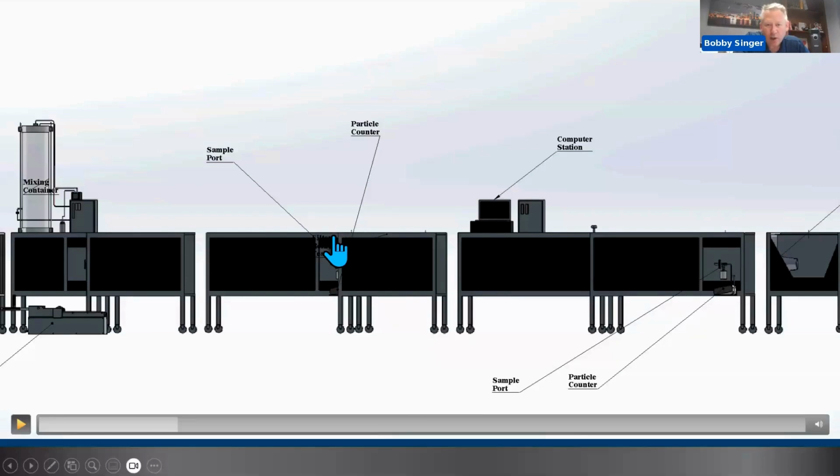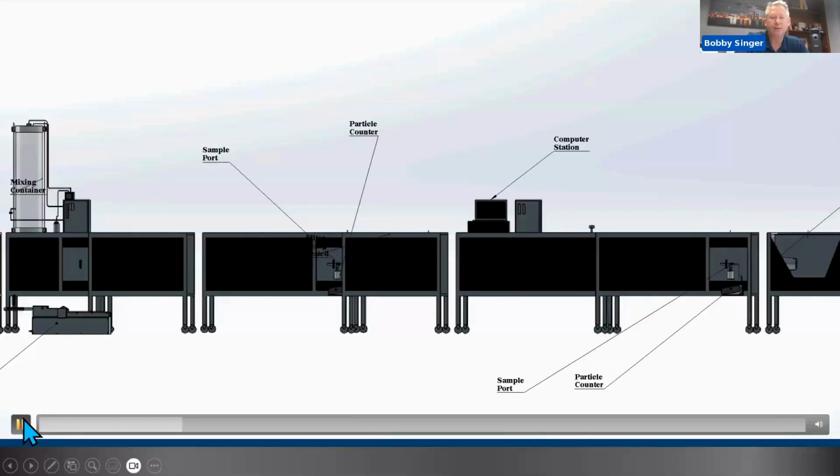Downstream of that is a flow orifice, which is how we measure the flow. You can see there's a static tap upstream and downstream of the filter here. Those would go to a manometer. That's how we measure the resistance to airflow, or the pressure drop, of the filter. And the same is done across the orifice. That's how we know how much flow we're pushing through the test duct.